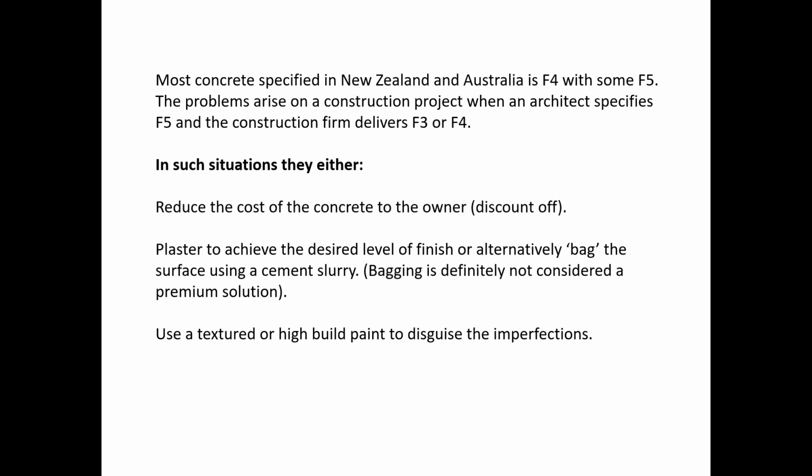You then have to fill all those holes, or you wanted a better finish in the first place. And that's where textured paints help hide some of those imperfections, and your filling and all of that sort of thing. So you need to have a good conversation with your concrete guys and the designers of the formwork, and sit down and tell them what finish you want and what finish you're prepared to pay for, and work with them to help get that.